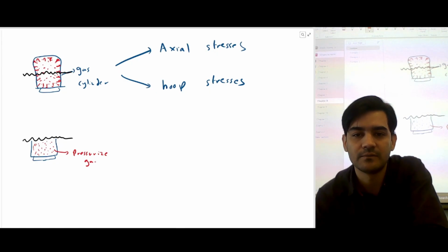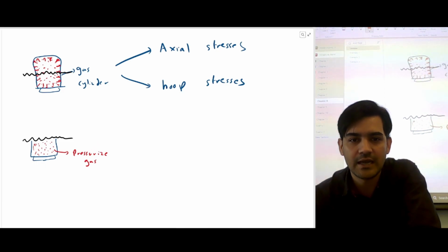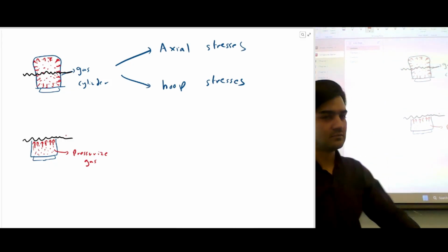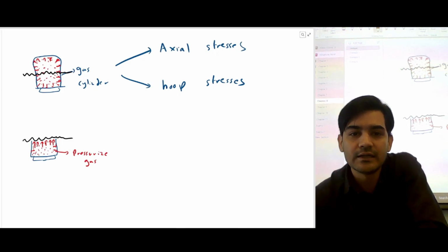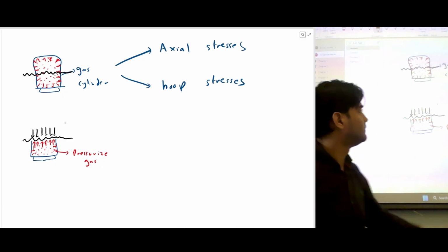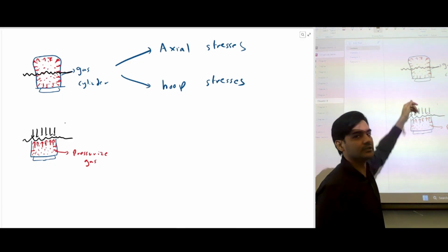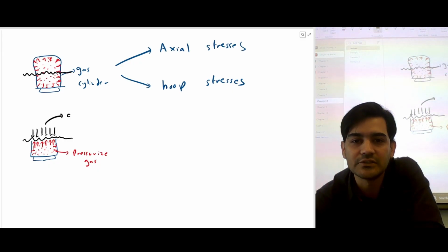These are like external loads. It's gonna be everywhere, but right now we're talking about the longitudinal. And as a result, we're gonna have internal loads and internal stresses. This kind of internal stress is called axial stress.